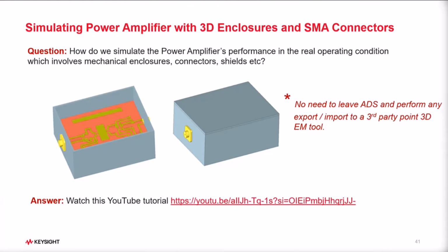All right. So let's continue and let's talk about assembly. Now, I meet many designers who get amazed when I show this picture to them and I ask them, can you do this kind of assembly in ADS? And 90% of them say no. They feel only third-party 3D electromagnetic tools, which are very popular in the market, only can do this kind of assembly. But at least from today onwards, just go with the impression that you could do all this without leaving ADS.